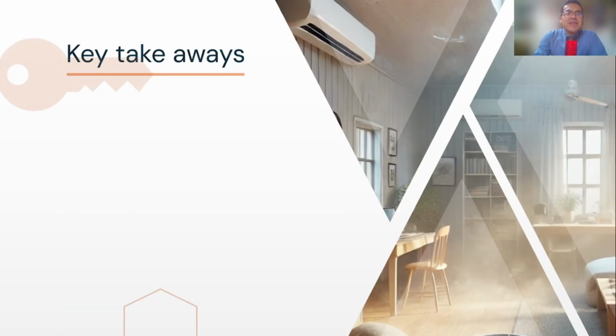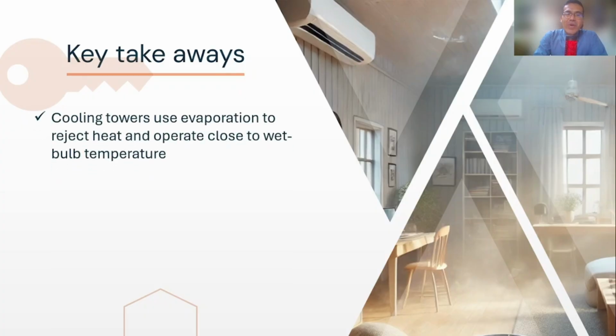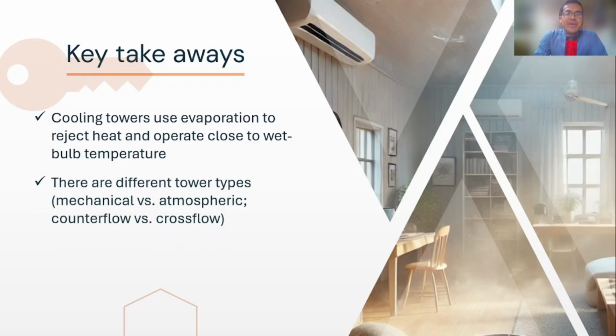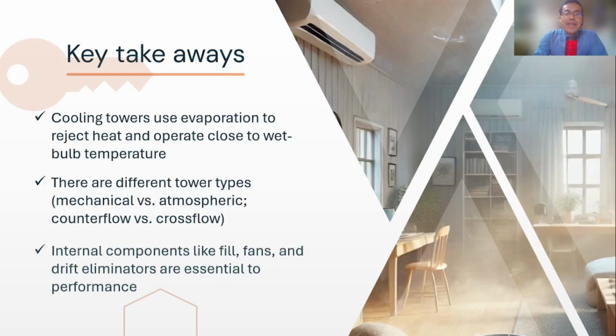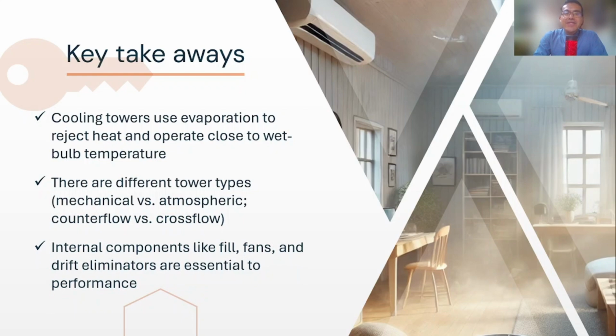loss. To summarize, cooling towers rely on evaporation to cool water effectively, using the latent heat of vaporization to operate near the wet bulb limits. They can be classified based on airflow method and geometry, with mechanical versus atmospheric and counterflow versus cross-flow configurations. And their performance depends on the internal structure, especially the fill, drift eliminators, and fan arrangement.